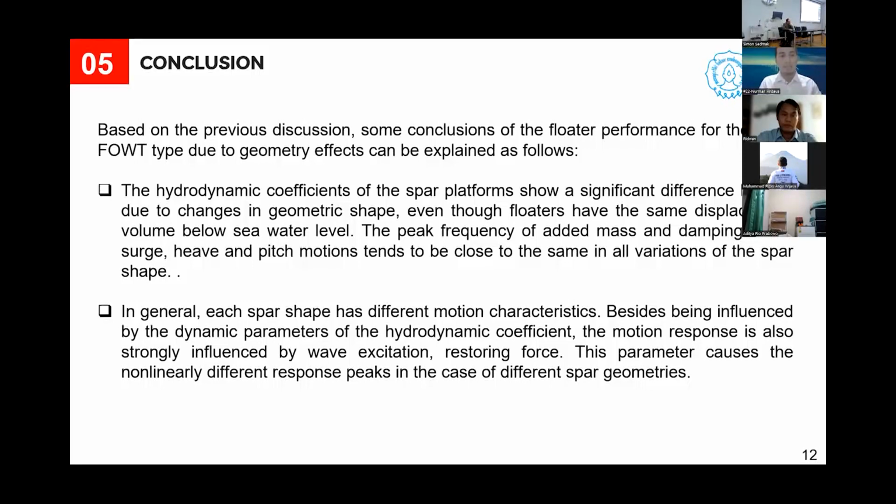Second, in general, each spar shape has different motion characteristics, besides being influenced by the dynamic parameters of the hydrodynamic coefficients. The motion response is also strongly influenced by the wave excitation and restoring force. This parameter causes the different nonlinear response peaks in the case of different spar geometries.